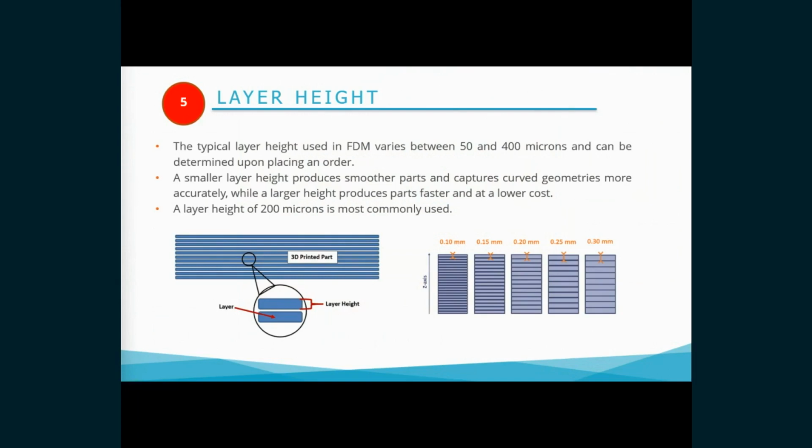One of the most common reasons for changing the 3D printer layer height setting is to increase print speed. Generally, increasing layer height will decrease the resolution and quality of the print. Layer height can be optimized for each print in order to attain a faster print speed while maintaining a certain amount of resolution.